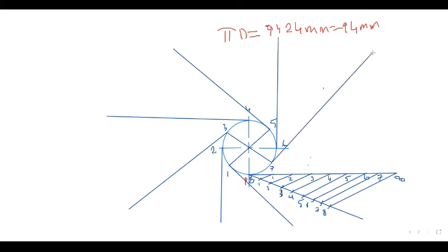And at 7 again we draw the 45 degree. And remember, first 1, 2, 3, 4, the tangent length must be more. The length you draw at 1, the one at 2 must be more, 3 will again be more, 4 will be more than the previous. Because now what we'll do, first by compass we measure P with 1, that is 1 to P. So by compass, if we draw, this will be, suppose, here, cut it.